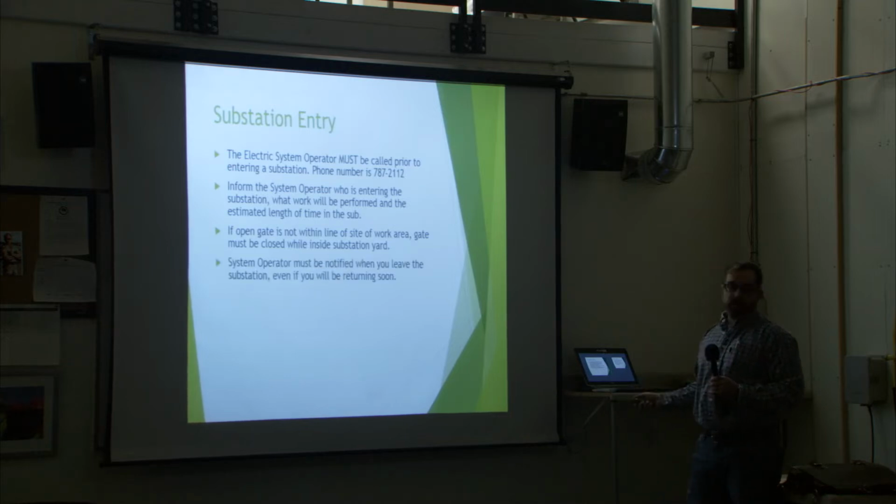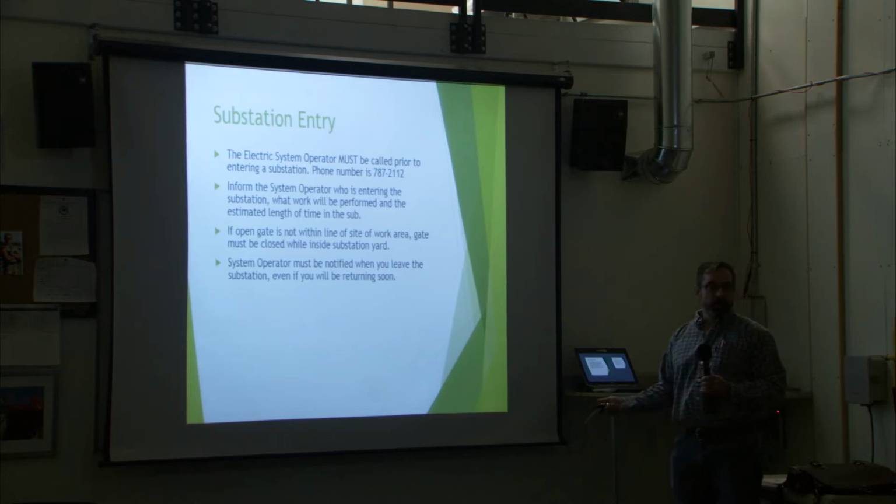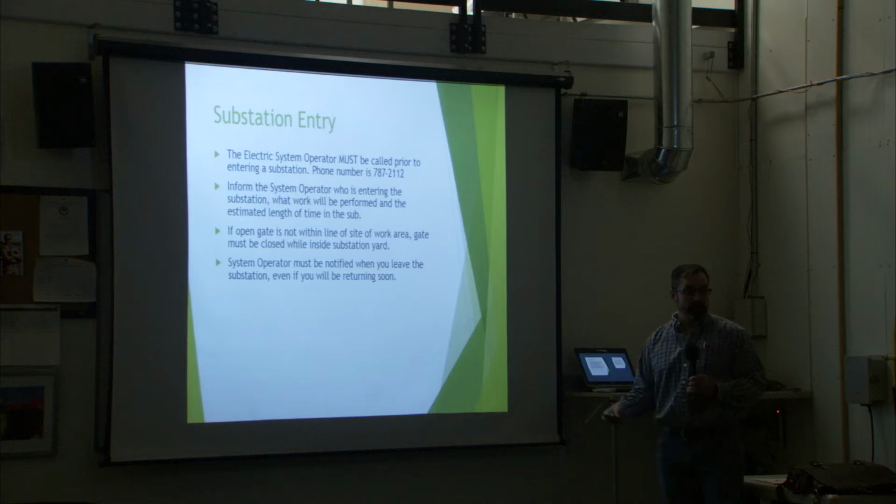You also need to notify the system operator when you're going to leave the substation, even if you're going to be returning. Say you're going to the restroom, and most of the subs don't have a restroom in them. If you have to go to the restroom, please inform the system operator that you're leaving.